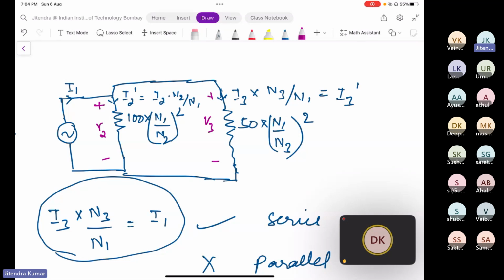No, see, here only the primary winding is catering to the MMF requirement of both loads, secondary and tertiary. Yes, sir, one thing is certain: N1 I1 should be equal to N2 I2 plus N3 I3. That cannot be questioned here.